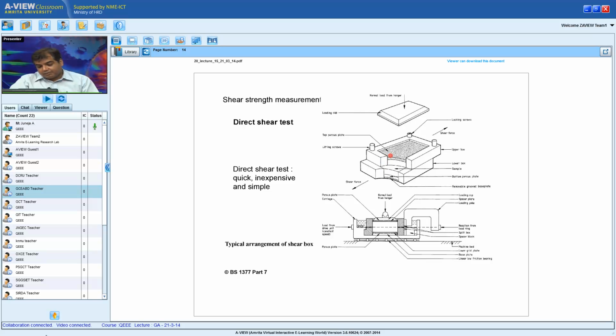We have not covered earth pressures, but for the time being, these horizontal stresses do not allow the soil to bulge. We call this the K0 condition. So the horizontal stress is K0 times the vertical stress. We will look at an example wherein we look at this K0 in greater detail.